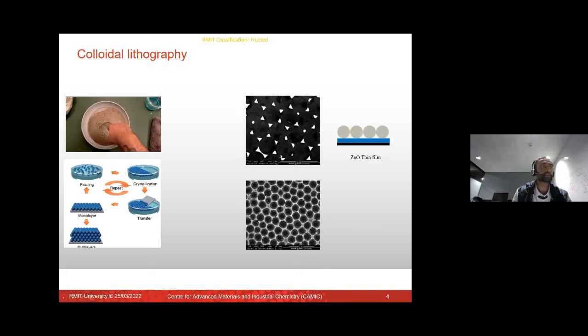And this is very simple. These two surfaces, all we've done is change the way we deposit our material onto our template. So in the top case, you see that we had our polystyrene structure on top of a zinc oxide film. And all we did was E-beam evaporation of our silver. And then when we removed our polystyrene template, we ended up with these star structures.